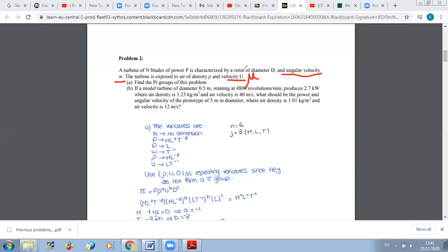Yes, because in case they are directly related. This is a turbine problem; it's very complex. It's not that if I have the velocity U, I directly determine W. It's a complex relation. It's not like when I have a rotation of a fluid at omega, where I can say that U is omega times R. But here it's not the case for the turbine. It's different. Because I have flow over the turbine with lift and drag forces, and due to the lift forces I will have rotation. So the relation between omega and U is not explicit; it's a complex formula. This is why I cannot put them as directly related and remove one of them.